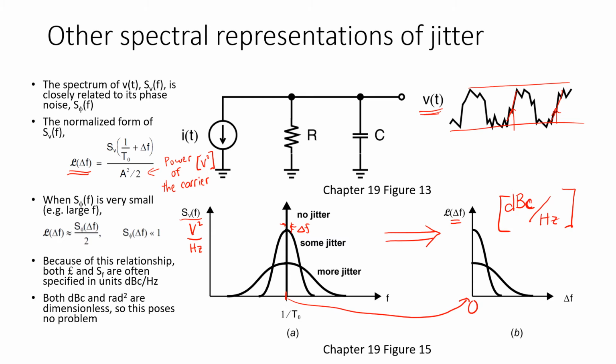So this is obviously not too difficult to measure, for example, in a lab, just using a spectrum analyzer. This can be measured. Now it turns out, although we're not going to derive this, that as long as the phase noise is not excessive, and by this I mean even for quite practical levels of phase noise, this script L is very simply related to the phase noise that we defined in terms of absolute jitter, just by this factor of 2 here.